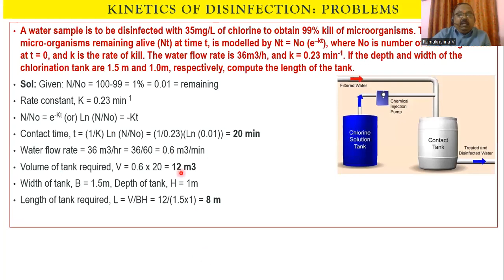And this is another calculation we use in the practical problems. Obtaining the contact time and then based on that, deciding the contact tank. Now, what you are going to see, you can see from this figure, the filtered water is coming from the treatment system, and the chlorine solution you are preparing is in one particular tank, and this is now added through a dosage meter, and these two are now combined for a contact time.